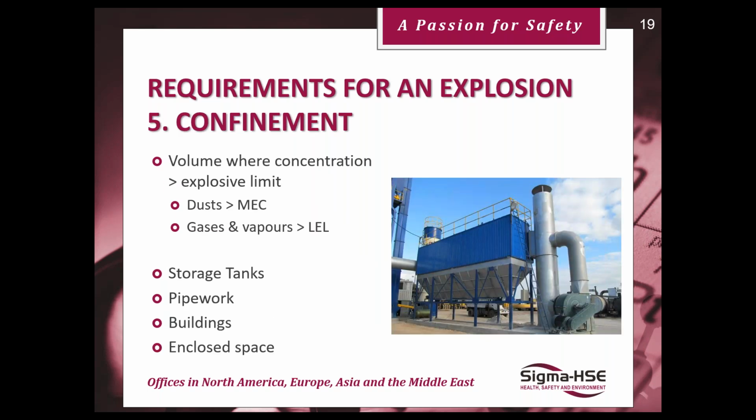And confinement, well, of course, most of our processing equipment is confined, especially when we're dealing with potentially dangerous substances. We don't work in the open, okay? But if we can limit that concentration, if we work with dust greater than the minimum explosible concentration, or with gases and vapors above the LEL, we'll be generating that flammable atmosphere.